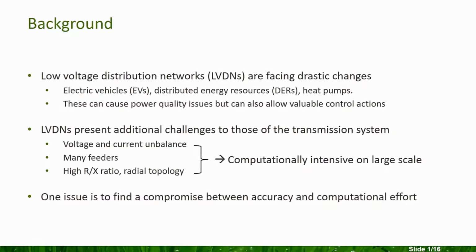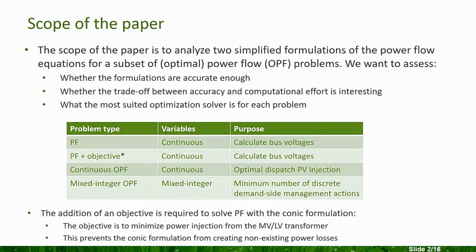So one interesting issue is to find a compromise between accuracy and computational effort. And for this purpose, this paper analyzes two simplified formulations of the power flow equations for a set of power flow and OPF problems, where we want to assess whether the formulations are accurate enough, and the trade-off between their accuracy and computational effort is interesting.